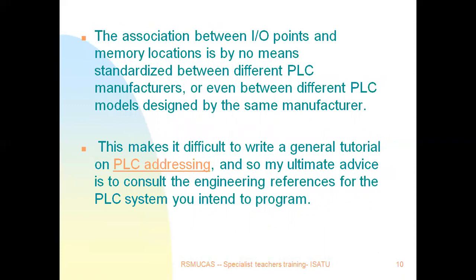The association between input and output points and memory location is by no means standardized between different PLC manufacturers, or even between different PLC models designed by the same manufacturer. Meaning there is no standard, but the system is quite the same; the method of writing or identifying the address depends on the type of manufacturer and the type of PLC you are using. This is why it is difficult to write a general tutorial on PLC addressing, so my ultimate advice is to consult the engineering references for the PLC systems you intend to program.